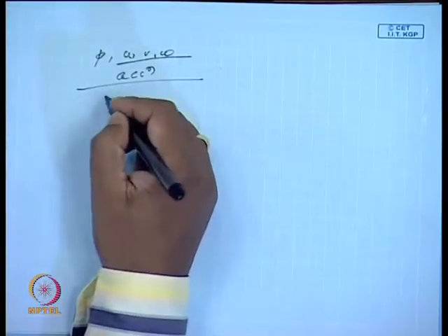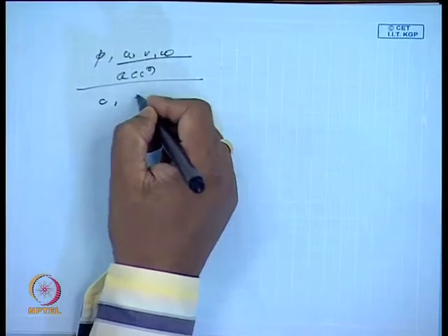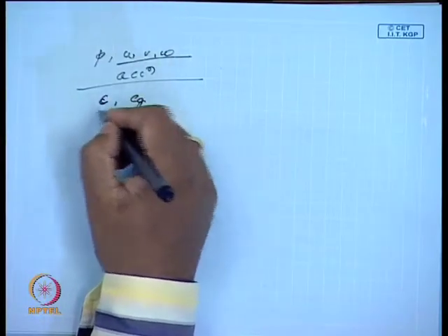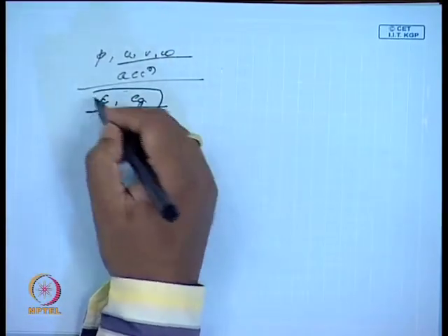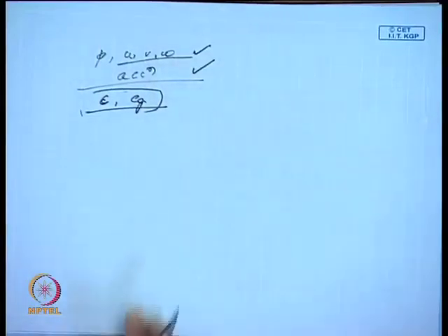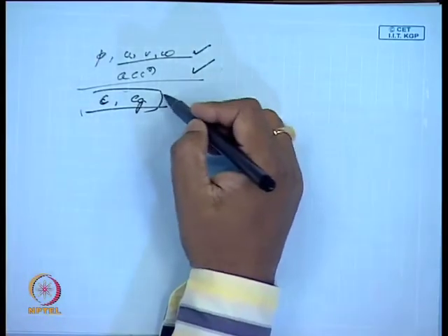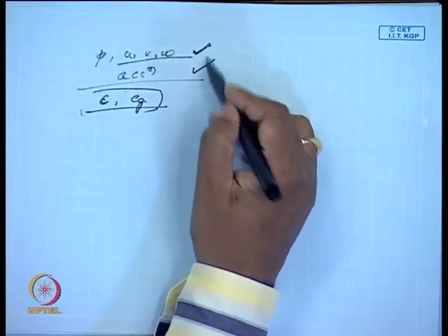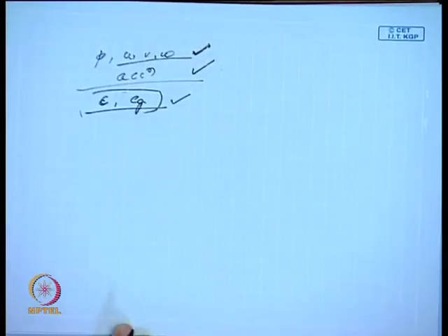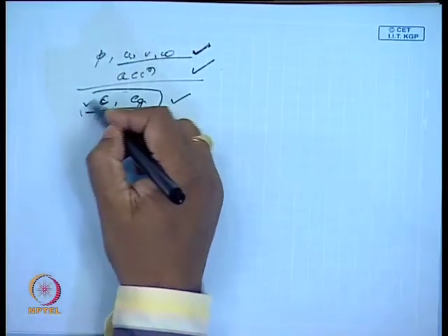On the other hand, we have the phase velocity c and the group velocity c_g. The group velocity talks about the energy propagation, and the others talk about the particle motion. It is very interesting that there are two speeds here: the speed at which the wave energy propagates and the speed at which the individual waves propagate.